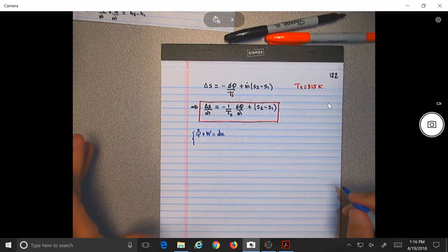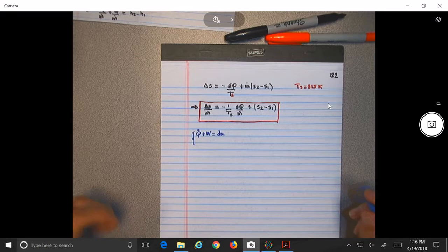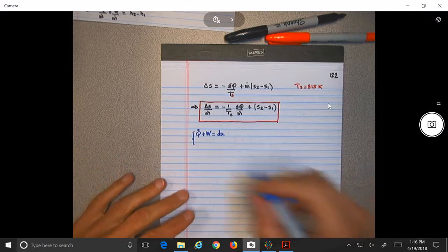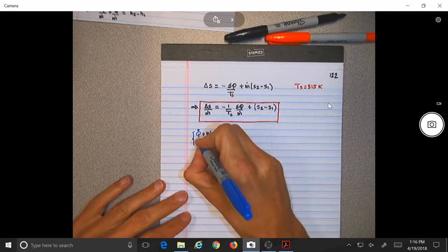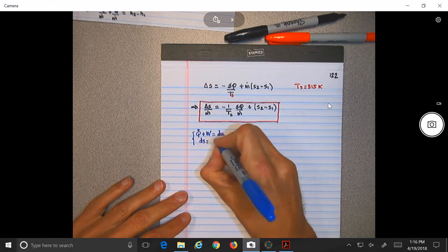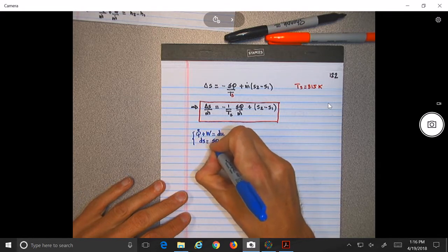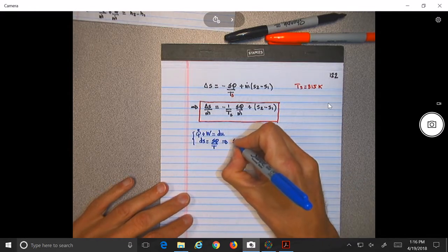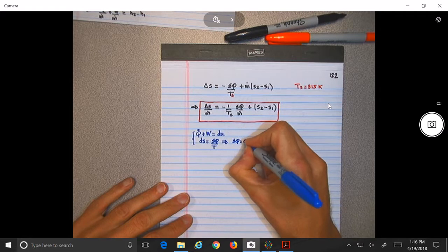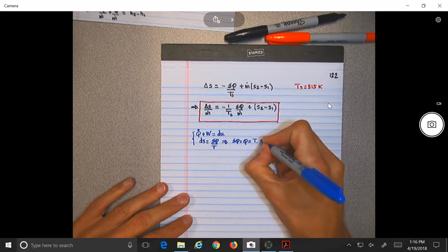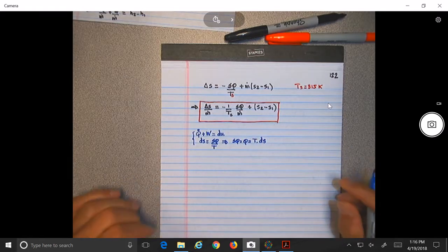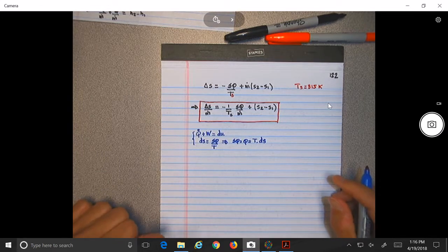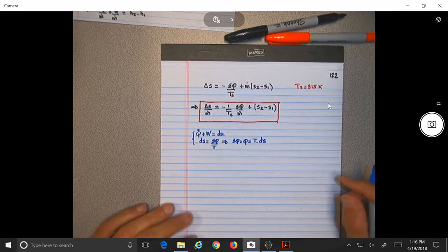First principle of thermodynamics was deficient in trying to prove what? The direction of the processes, no? What is that equation that helps us to define the direction of the processes? So ds equal to what? dq over T, correct. So we get from this one that delta q, which actually is our q, will be equal to what? TDS. Do you remember we derived all those TDS relations, no? Which is basically what I'm doing again.